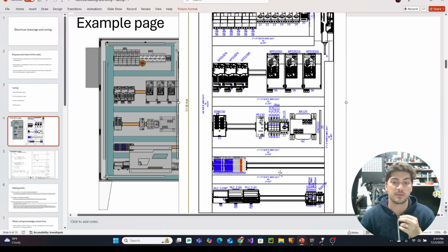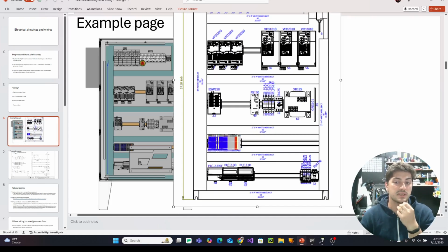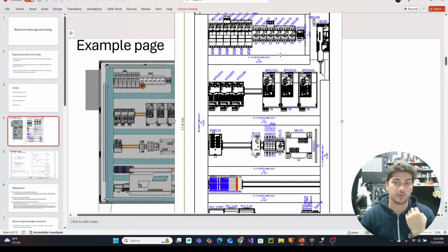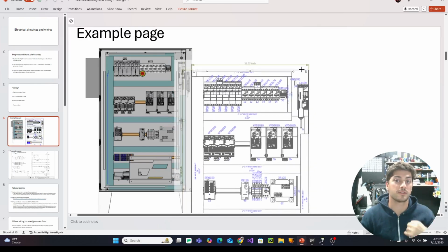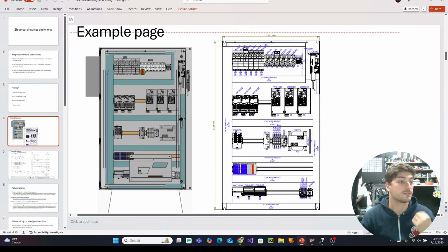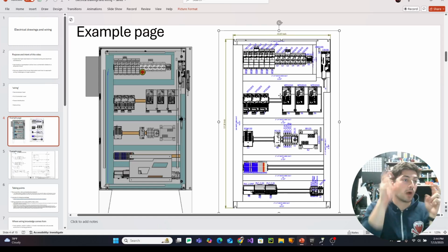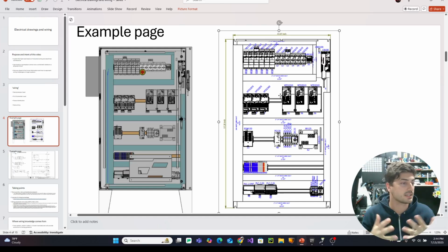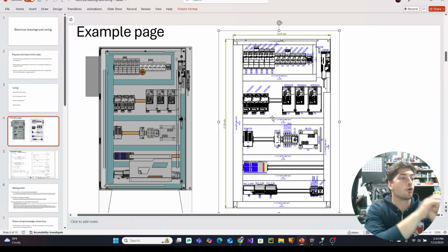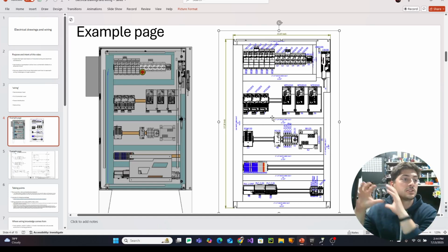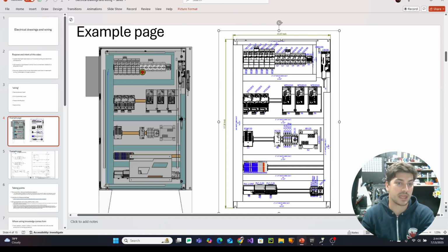Your switch in the middle row, terminal blocks, PLC components. And so this is a labeled one that still has all of the physical components in their correct physical locations. But this one is correlating a wiring label like VFD 1070 or whatever, some way that it's going to get referred to in this control package. And it's correlating that physical component to a drawing package page that we'll find.